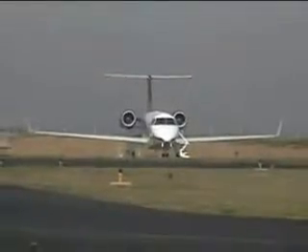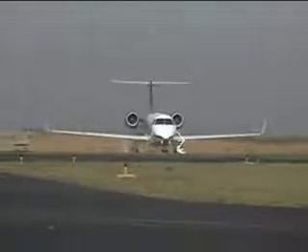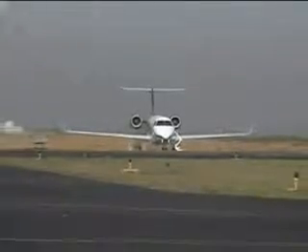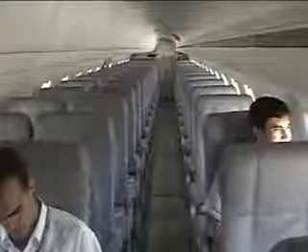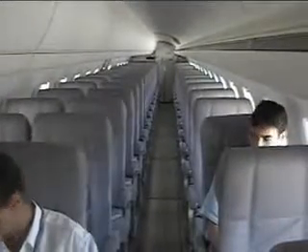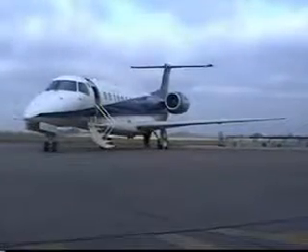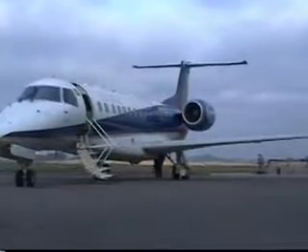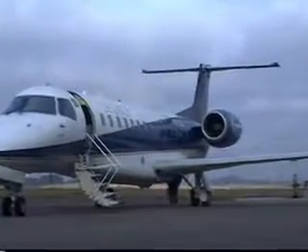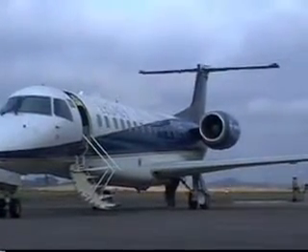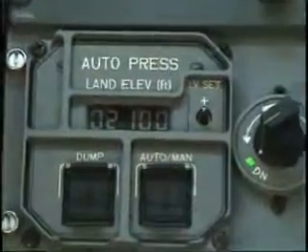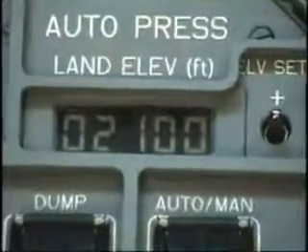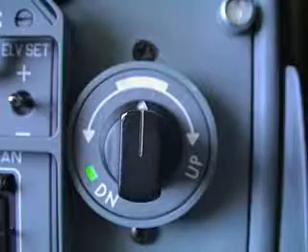In the Embraer original jets, like in other pressurized aircraft, the cabin and cargo compartment are incorporated into the sealed fuselage, capable of containing air under pressure higher than outside atmospheric pressure. Pressurized air is pumped into the fuselage by the bleed and air conditioning systems, and is released from the fuselage by the outflow valves. The adequate signal to control the outflow valves comes from a digital controller in automatic mode, or from a manual controller in manual mode.